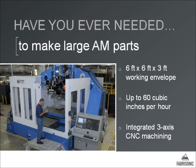Another differentiator of ultrasonic additive manufacturing is the build rate, which greatly affects the build volume. This is a picture of our largest machine. It has a working envelope of 6 feet by 6 feet by 3 feet, which in the additive world is a very large envelope. We can build up to 60 cubic inches an hour if we're making a straight flat plate.